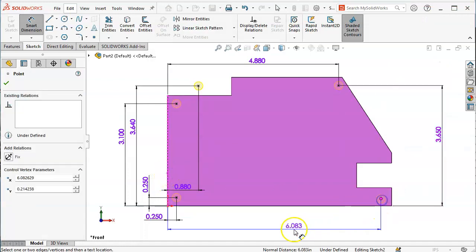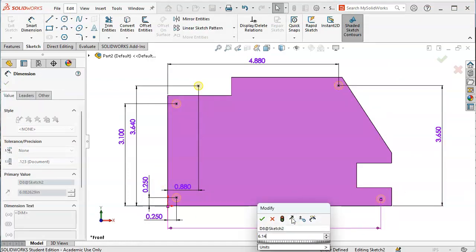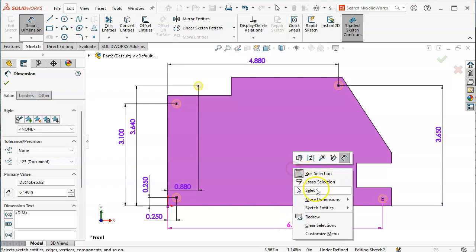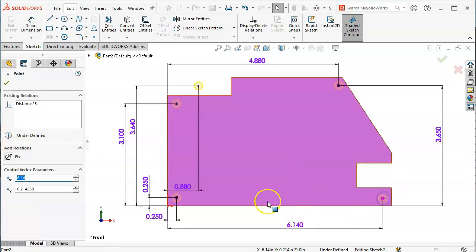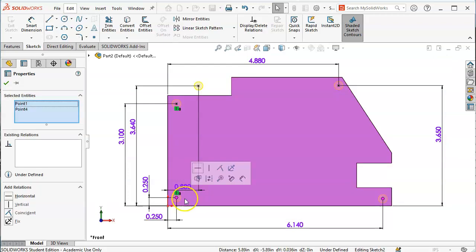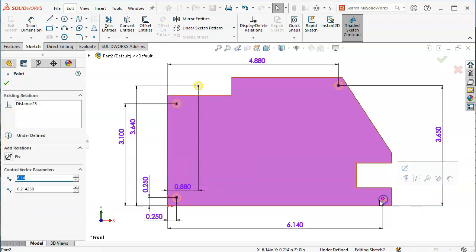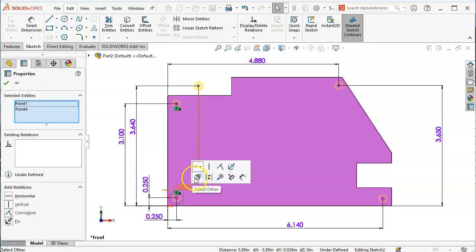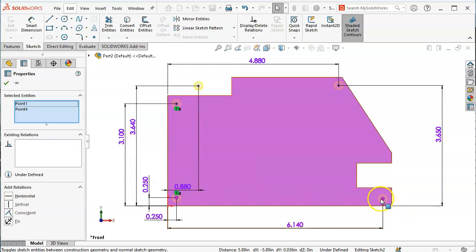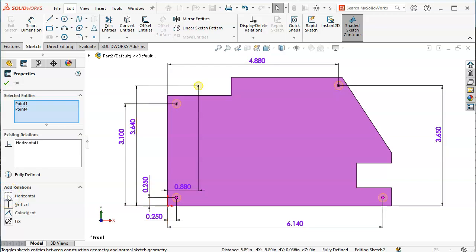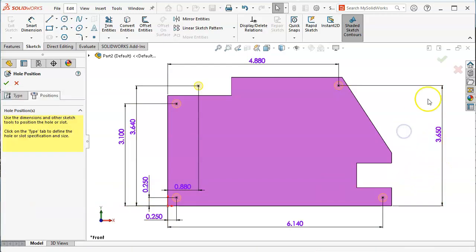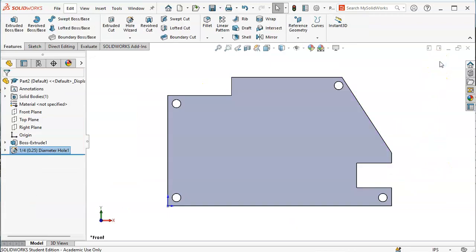And then we have another situation where I can right click, go back into the select, which is the same as hitting the escape, and control select. All right, so whichever way we go, select, control select. And if this is already highlighted, already has the point there, then I don't need to reselect it. I'm basically deselecting it at that point. When I set that to horizontal, they'll jump into position.